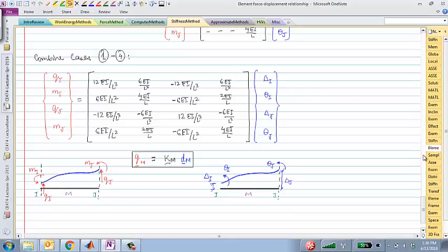Now, let me ask you a question. For the truss element problem, what did we do after we derived the force element displacement relationship? If I give you a truss problem, the first thing you compute is that +1, -1 thing for each truss element. After that, what do you do? Marisol, go ahead. Yeah, you put it in the global, but before that, you also have to transform it because truss elements may be inclined in some random direction, right? Here, the good thing is there is no transformation needed.